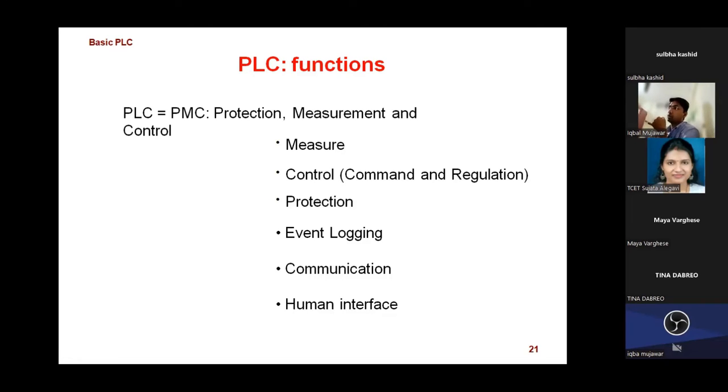Event logging: if someone wants to log what process occurred, or how much time it took when it was completed, that kind of event logging we can do over here. Some kind of communication, this part might be explained in the next session with the help of SCADA. There also we use this kind of PLC, and we can communicate, we can restrict the control, and we can control the complete supervisory control data acquisition system and human interface. That is also possible, and that is also a function of PLC.